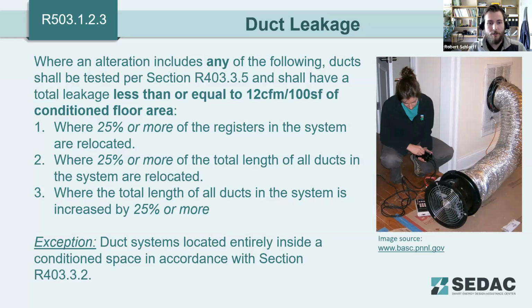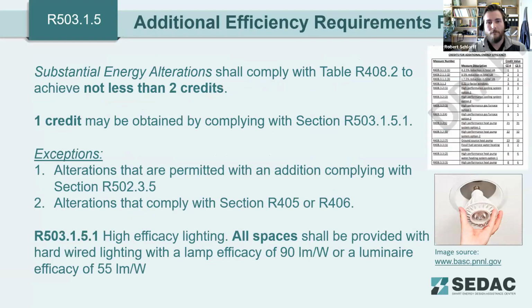There is also an exception to this requirement: duct systems that are located entirely inside conditioned space in accordance with R403.3.2. So another point from the code there is that if you bring those duct systems inside conditioned space, we'll give you a little bit of credit there. You don't have to meet some of these more stringent requirements.